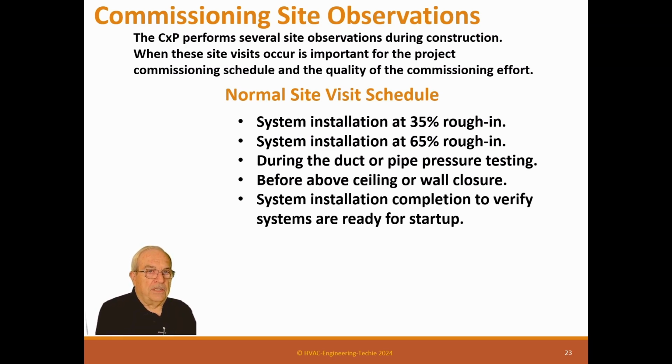The system installation completion is to verify systems are ready for startup. This way you can kind of help the general with his schedule. I've seen it many times when I've been at the site and say, well, this thing's not ready for startup. And you go to the meeting and the general says, yeah, we're starting up tomorrow. And I go, no, there's no way you can start up tomorrow. The reason is because the GC is an expert at some things, but not all things. And normally they lack experience with HVAC and controls. They don't have the depth of knowledge to be able to tell if someone's blowing smoke at him, but you should.